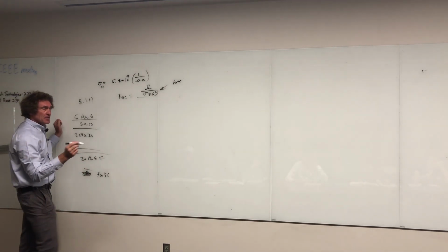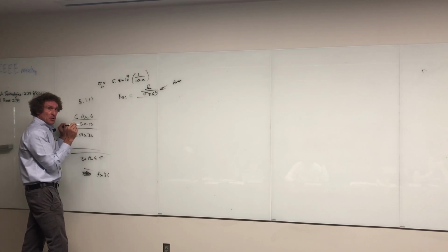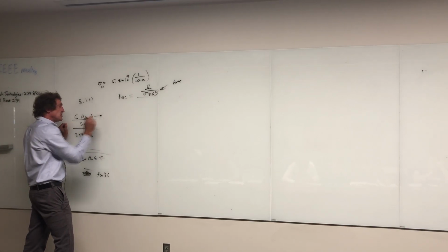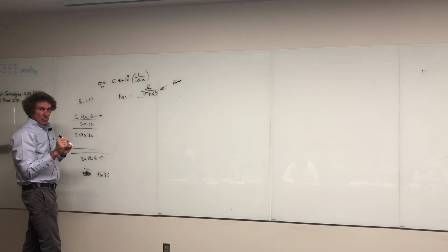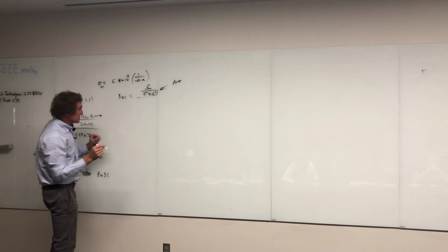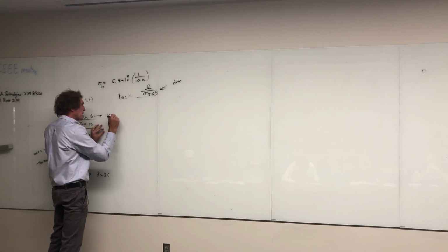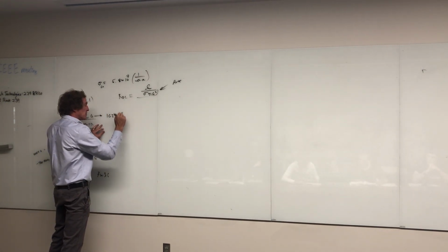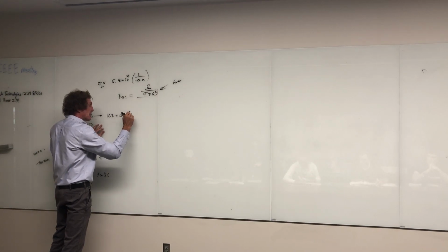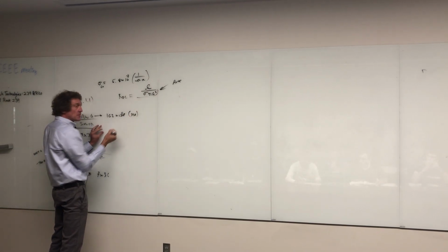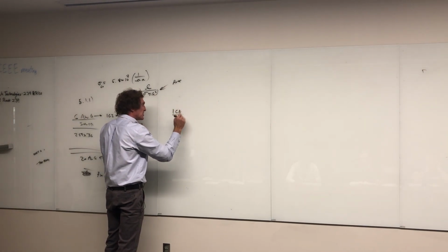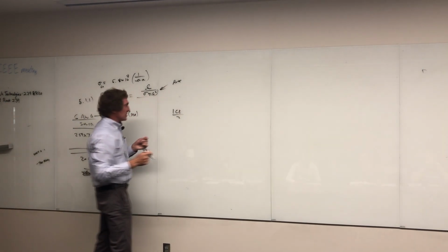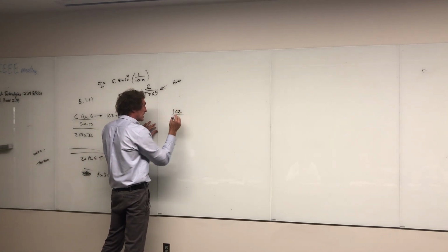So now you have the table right there, right? When you look at 6 AWG, it'll have a diameter there in mils. Correct, class? What do you get for mils, the diameter? 162 mils. So if you take this 162 and divide it by 2, now you have the radius. We could have used diameter in there, but I like sticking with radius.